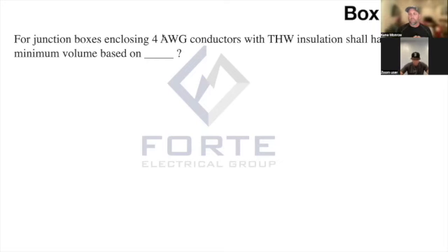Now, if you have that same box, and instead of going from the right side to the left side, we come in from the right side and we go down, we use it as an angle. We multiply it times 6 of the largest conduit.